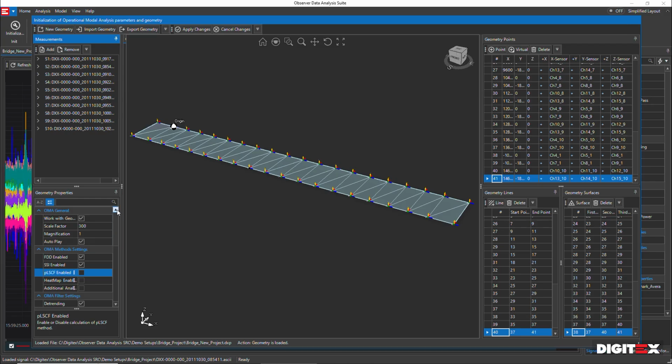And like the previous time, once we select the appropriate pre-processing characteristics and decide which type of filter and decimation type to use, and all the parameters needed for the OMA analysis, we can just click on apply changes, and the system will start calculating the initial process of the modal analysis, which is again calculation of SVD, singular value decomposition, and stabilization diagrams.